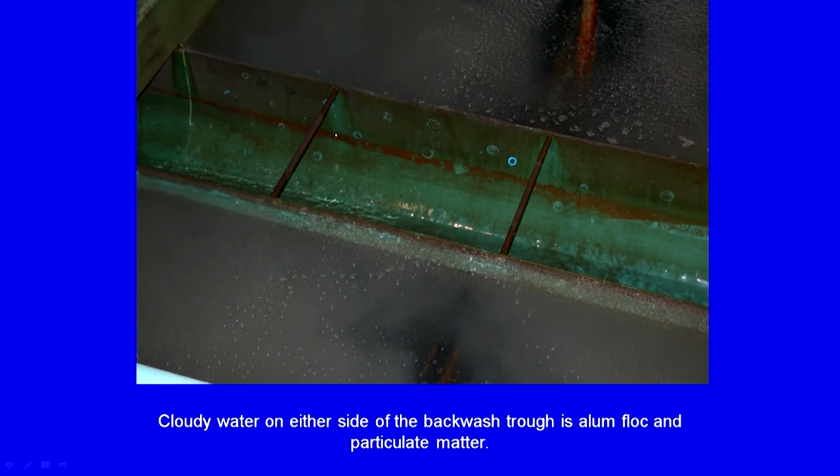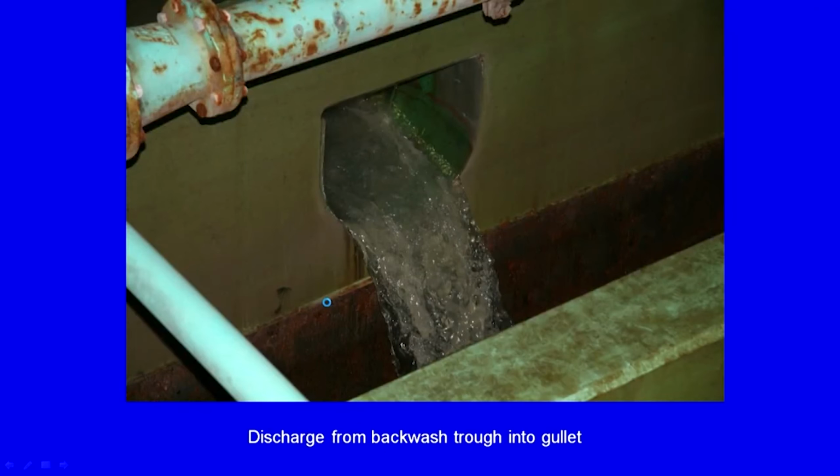We see cloudy water on either side of the backwash trough. Why is this? This is alum floc and particulate matter. It looks like before this they had added a coagulant, which was alum. So, when they are backwashing, you see that this cloudy material is alum floc and some particulate matter on the surface, and from the backwash trough it is being collected in the gullet.